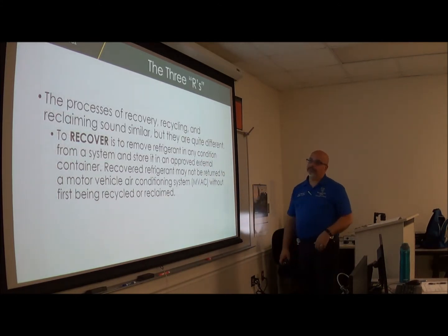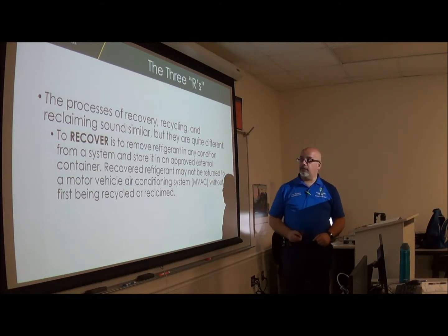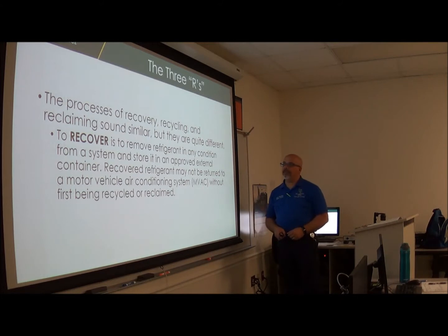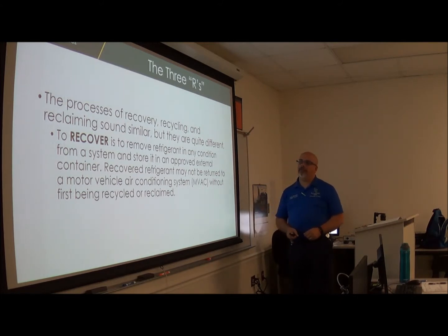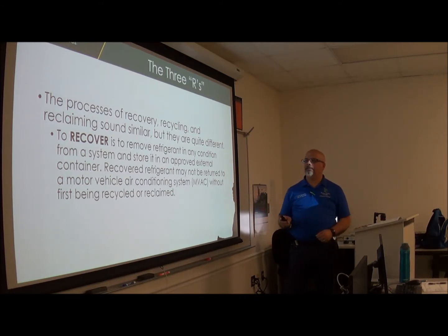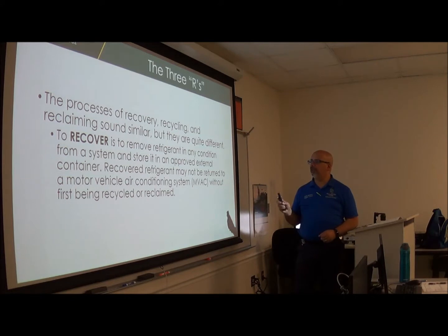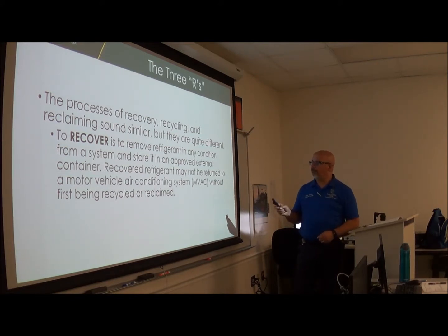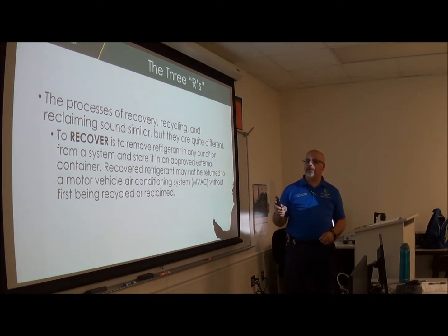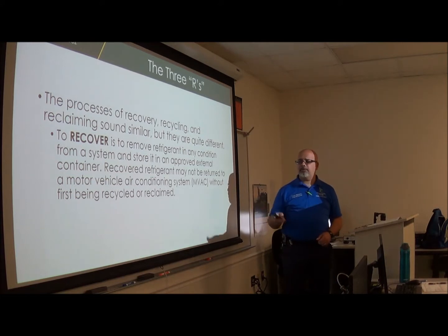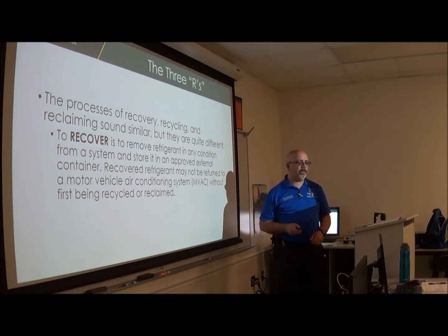The 3 R's. The processes of recovery, recycling, and reclaiming sound similar, but they are quite different. To recover is to remove refrigerant in any condition from a system and store it into an approved external container. Recovered refrigerant may not be returned to a motor vehicle air conditioning system without first being recycled or reclaimed.